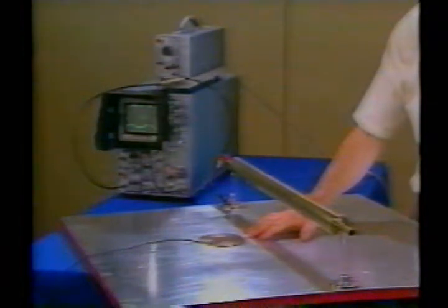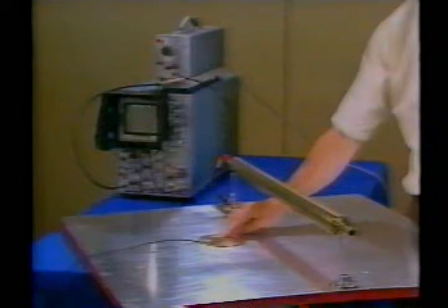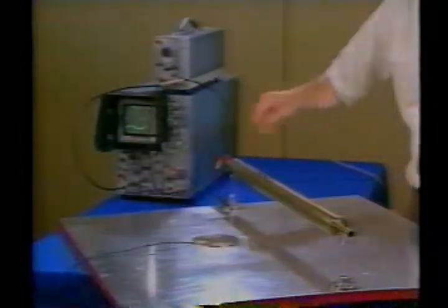It is therefore proportional to the voltage of the cylinder. Conservation of charge requires that the probe current be the time rate of change of the charge on the probe surface. It follows that the voltage induced across the internal resistance of the scope is proportional to the rate of change of the applied voltage.